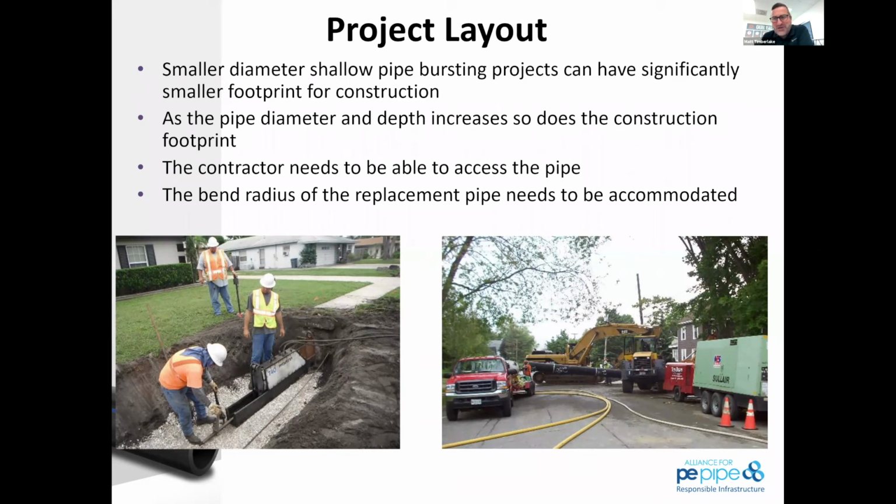I'm not used to seeing pipes 3 feet deep in Maine, but as the pipe diameter and depth increase, so does the footprint. So with HDPE pipe and even with the pipe bursting equipment, the deeper we go, typically those excavations are going to grow a little bit longer. And a lot of that is to get the radius to get the pipe down into the ground.